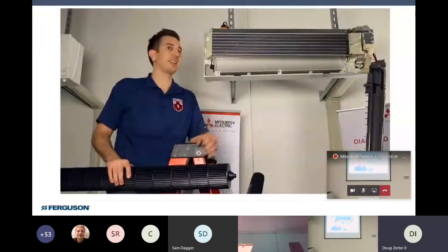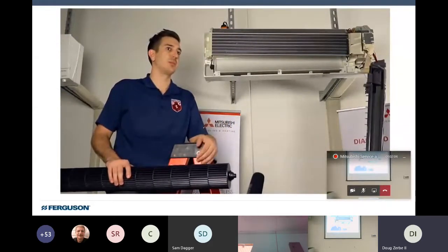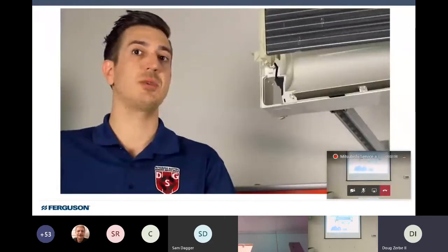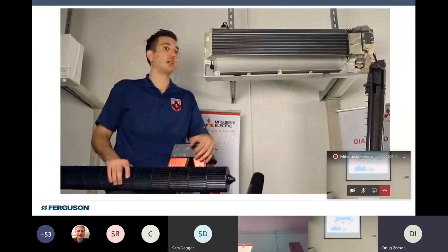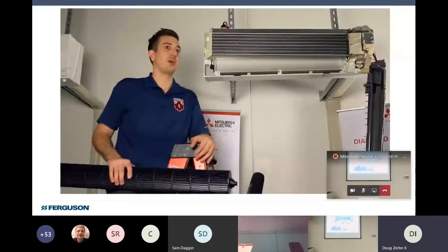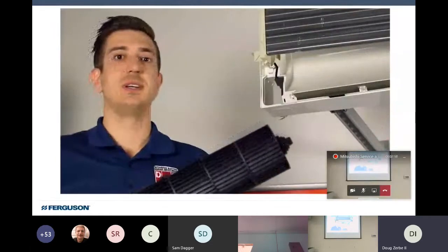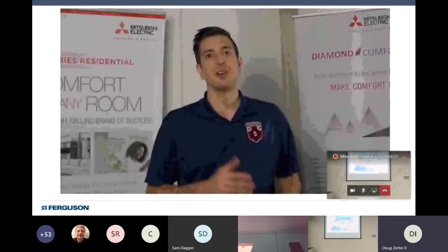And the third is to locate the set screw that holds the blower wheel onto the blower motor. The set screw has no dedicated spot, or commonly referred to as a flat spot, on the blower motor. This helps when putting it back together. You don't have to worry about where it's aligned. And lastly, to reassemble it, just reverse the steps we took to remove it.